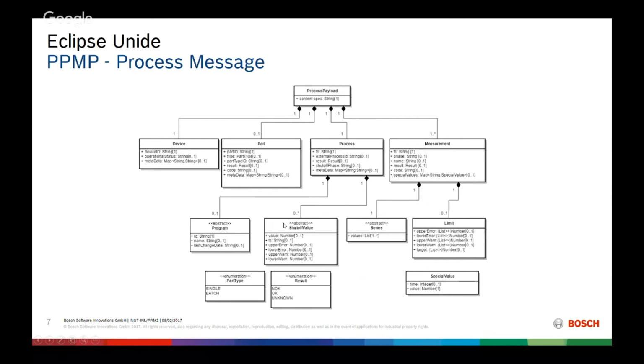And you can set here a couple of shutoff values. For instance, when you have a tightening process, you have a shutoff value at a specific torque. Please end up the process. So this shutoff value you can transfer or set here with the value, the timestamp when it occurs, and maybe also some upper and lower error and warning levels.